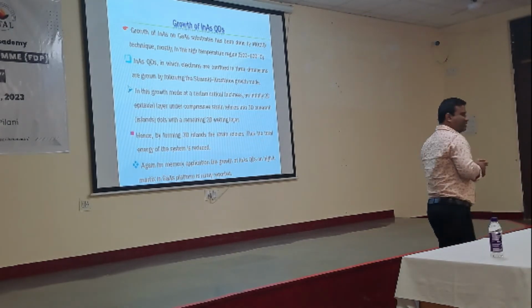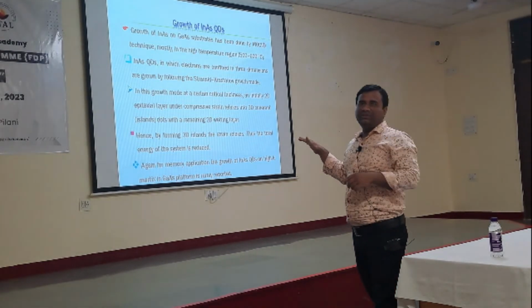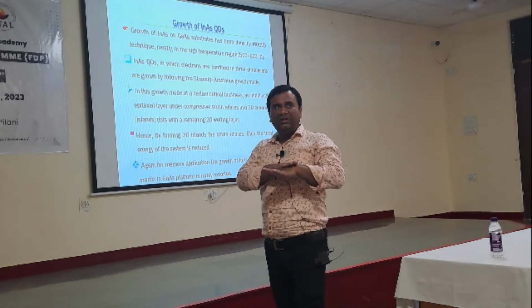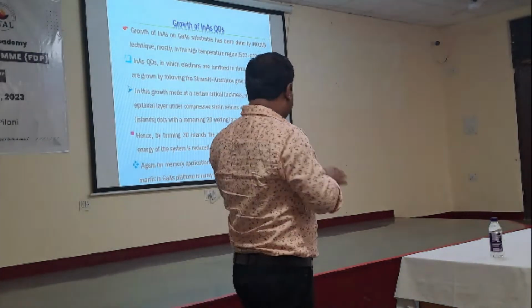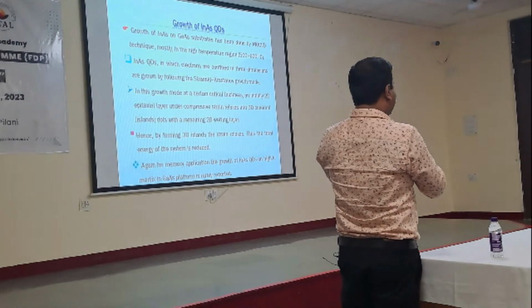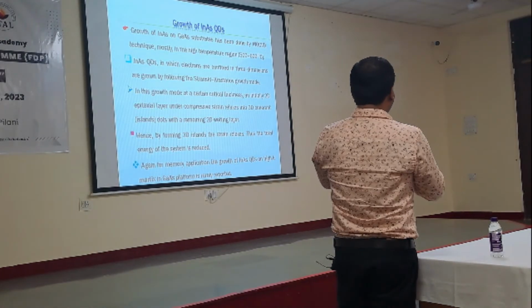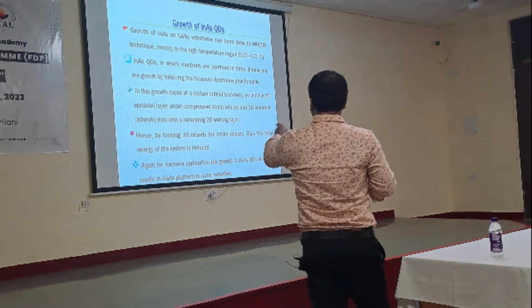Every system wants to release energy, so because of minimization of surface energy, the deposited 2D thin film relaxes into 3D islands. So initially a thin film will be formed. That thin film, because of the surface energy minimization, will then form 3D islands.